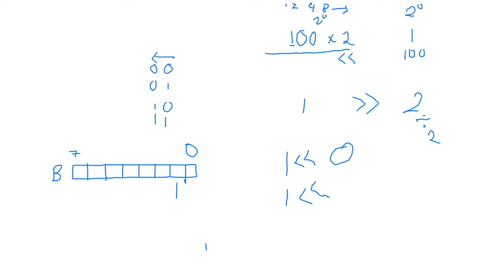Get power into the computer. So let's say if we shift that 1 by 1 bit, it is going to be the bit that we specified on there. So this is bit 0, this is bit 1. So let's say if we want it to be in bit 5, we can simply access bit 5 straight away by doing this, which means we start counting from 0, 1, 2, 3, 4, 5. So this is a pretty straightforward way of accessing individual bits of a given data.